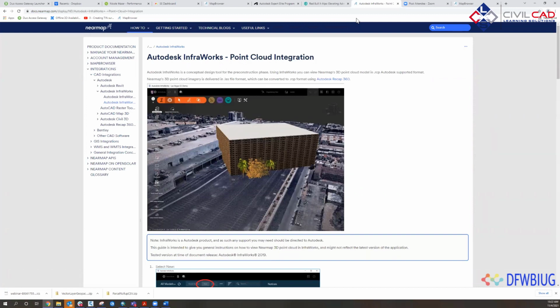Yeah, so we do offer a custom service, which when you stream that into Civil 3D, you're getting our entire US coverage footprint. North America, actually, so you're getting Canada too. And then within Civil 3D, you're able to geofence that. So my recommendation for people who are changing the area on their WMS would be to start with the simple service, have those layers turned on, and then geofence within Civil 3D the areas that you want.